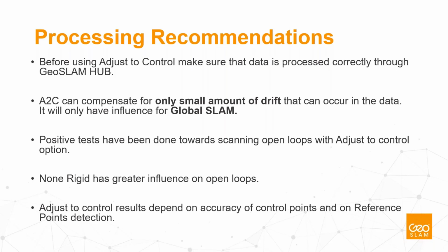Of course, the results of the adjust to control will differ, and there's a lot of factors that can influence it. Main things, accuracy of control points. We have actually tested quite a lot of different sets of control points with a different level of accuracy, and that is quite significant difference. If you are using very low accurate control points, you might see some problem in the point cloud as a result from adjust to control. So it is quite important to have good accuracy control points.